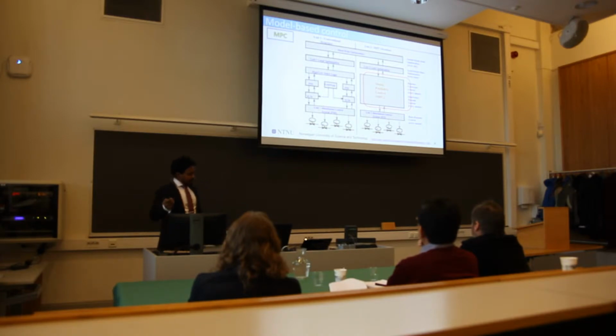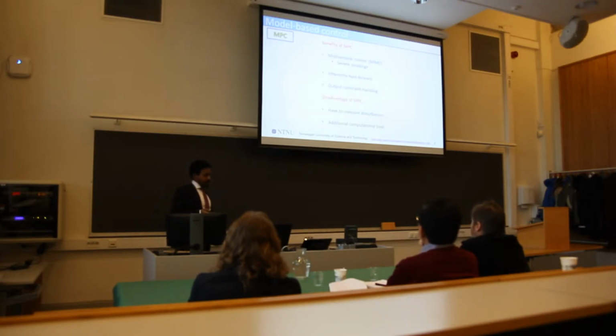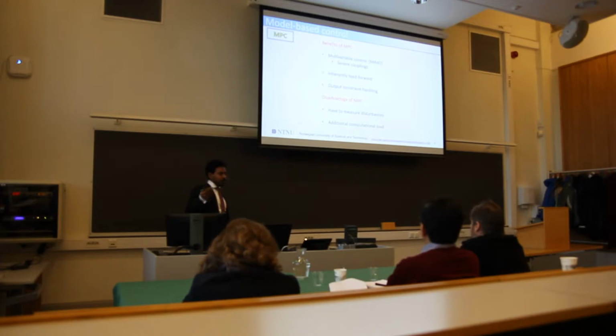Now, what are the benefits of MPC? Well, no one tries to replace their old functioning system with something new unless they have something really big to achieve. And MPC does offer something called multivariable control. If you have a mismatch in the number of inputs and number of outputs, and you don't know how to couple them, and there are severe couplings, you affect one input and it affects 5 outputs.